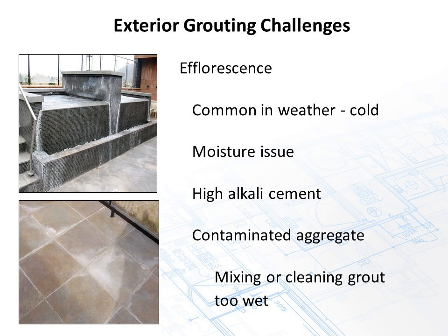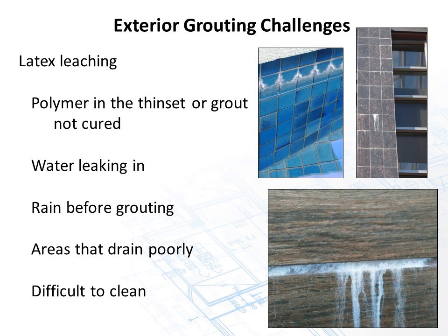It could be contaminated aggregate. You could have a mortar bed that's installed where the aggregate was just full of salts and mixed with the cement. Then you install the setting material, grout, etc., and all that moisture from the mud bed comes up through the grout. Mixing or cleaning the grout too wet can also affect this because it extends the open time and really puts this material into solution. It's cleanable generally, but not fun.